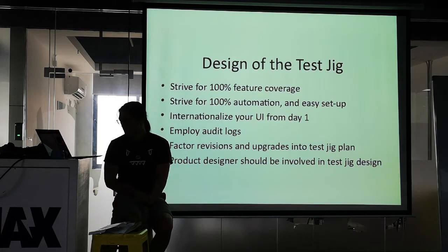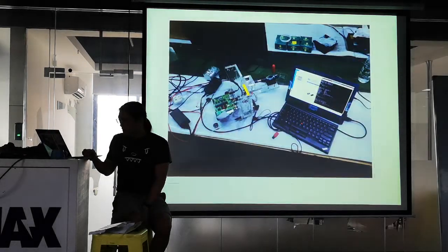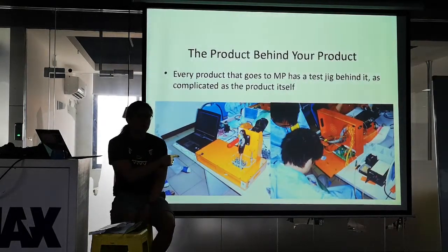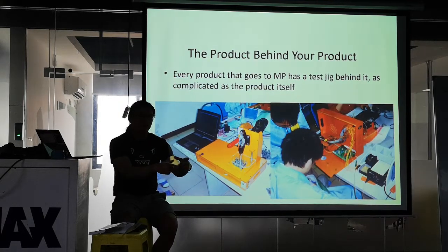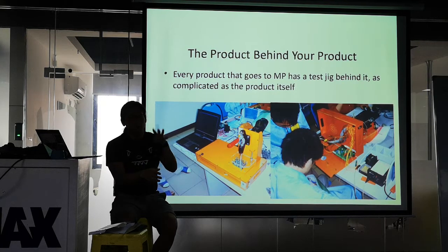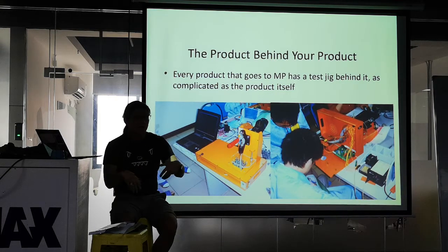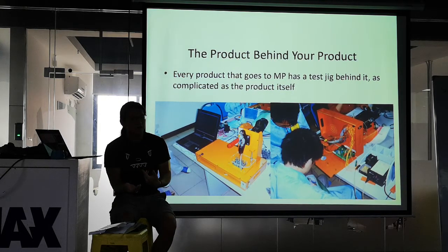There are people who specialize in building the orange boxes. These things you don't have to build, right? So don't waste your time 3D printing parts and CNC machining, putting pogo pins in. Basically, take your Gerber, say here's the test points, and send it to a factory that says I would like a jig that I can put the PCB into, with the alignment pins and the clamp and the pogo pins, and I'll put the rest in myself, right? Usually I'll specify to have some standoffs for a Raspberry Pi or something like that on the inside. And then for about $100, $200 and a week here in Shenzhen, they'll send you that thing, right?